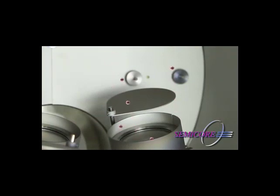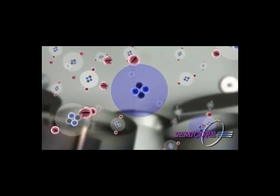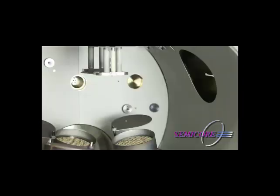Now the conditions inside of the chamber are ready to begin the process. A negative electrical potential is applied to the magnetron, which is the cathode, and the ground reference is the chamber, which is the anode. This electrical potential will cause free electrons to accelerate away from the magnetron. When these electrons collide with a process gas atom, they strip the gas atom of an electron, creating a positively charged process gas ion. The positively charged ion is accelerated towards the magnetron. This ion carries enough energy with it to knock off some of the magnetron's target material. This target material will then collect on surfaces in the path the magnetron is directed at. This is how material collects on your substrate.